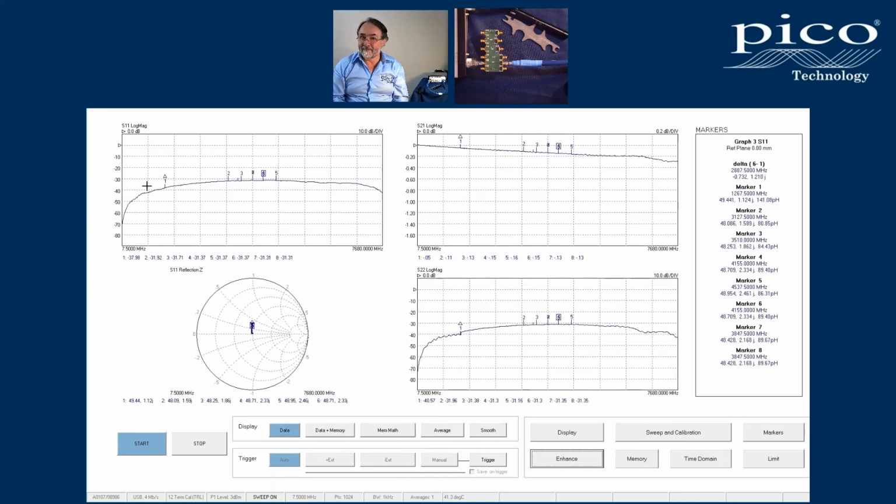But what have we just done? We've just corrected the line measurement to be the same at this frequency as the load resistors, or as the TRM resistors. It gets rid of our discontinuity, and we may wish to do this, but that may not be a better measurement for the application that we're doing. So some users will want to make these sort of corrections and can using our software, but it's not necessarily the right thing to do. Okay, let's leave that in place.